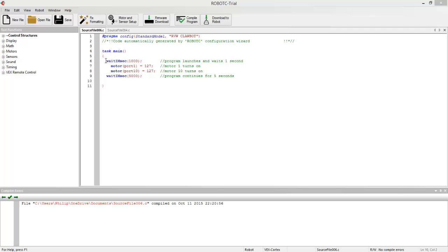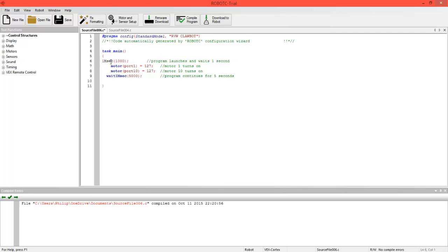Firstly, there are no wait commands because you are the controller and therefore you're not waiting for the function to happen. So what we can do here to modify our file is to delete the wait commands. If we delete both the wait at the start and the wait at the end, we now have two lines of code that say that the motors will turn on at 127 RPM. But again, this is not under our command. We need to decide how to do this.